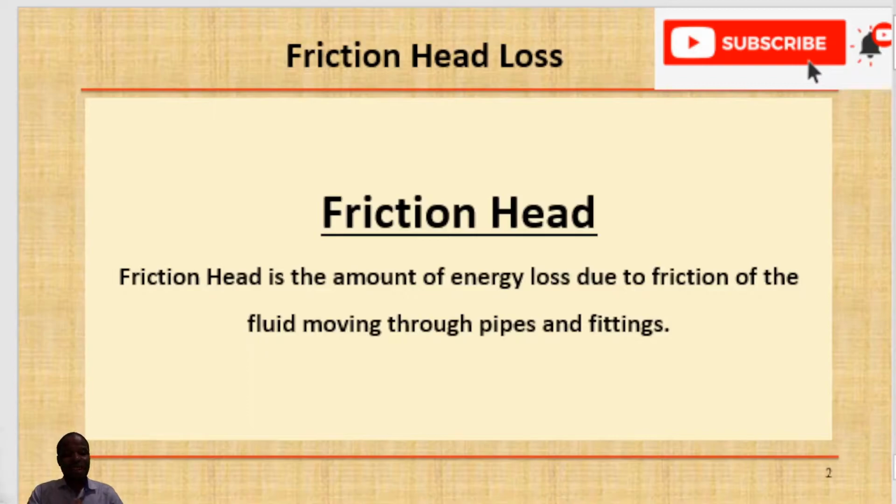That's the friction head, the friction head loss. The friction head in your pumping system is the amount of energy loss due to friction of the liquid moving through pipes and fittings. So we are going to be looking at how you determine that amount of energy loss due to friction for a particular pumping system.